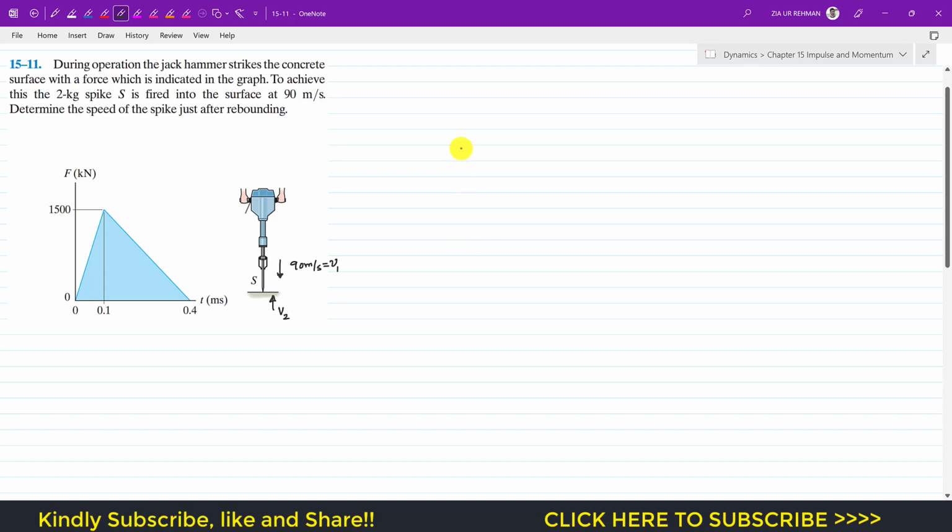Now we have to apply the law of conservation of momentum, which says that the initial momentum, that is mv1, plus the impulse due to the external forces, is equal to mv2. The mass of the spike is 2 kg, so we write 2 into v1, which is 90, and the external force is from the surface, so the external force on the spike will be acting in the upward direction. Let's say this is that force F, which is given here in the shape of this graph.